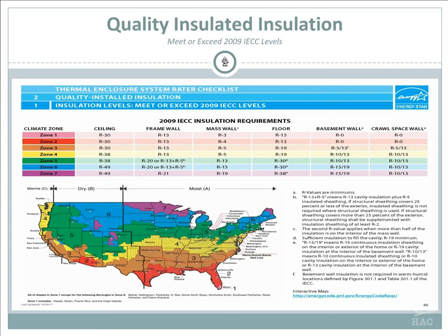So when you get the math and the calculation, if you look over to the far right, it'll say an R10 over 13. So this is a crawl space wall. What you want is an R13 on the inside wall, and then an R10 on the exterior. So if you insulated your slab or your foundation, you would put an R10 exterior board on that outside slab or foundation, and then you would insulate the inside with an R13 to give you what you need to meet that code.